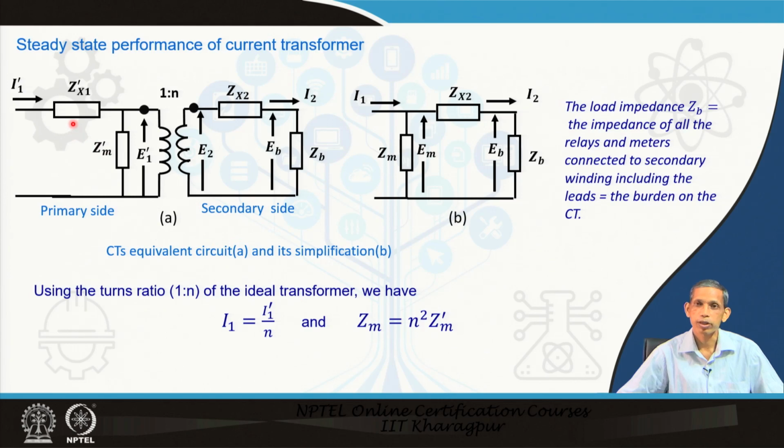That is independent of the CT. It depends upon the load and the system operating condition. Therefore, the current injected to the CT depends upon the system condition, so for this transformer the input signal becomes a current source kind of thing. Right? So, the equivalent becomes a current source.